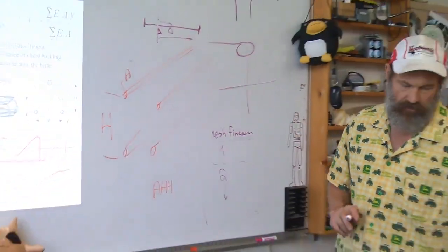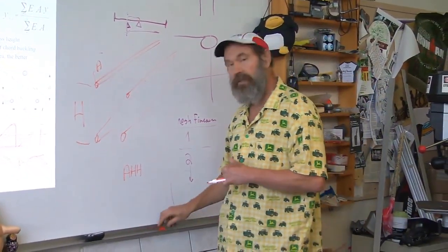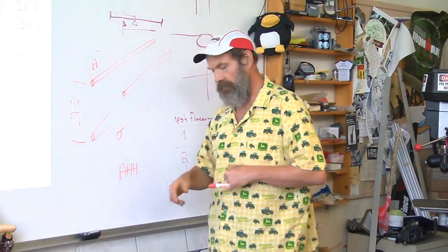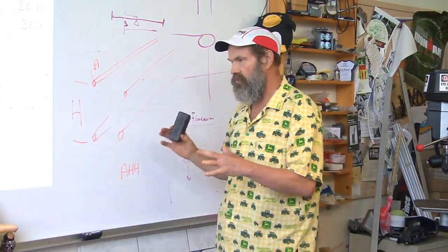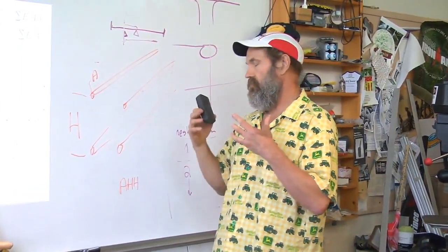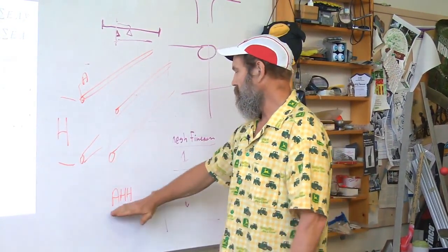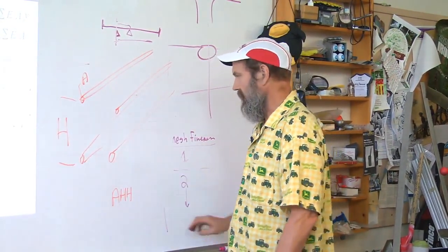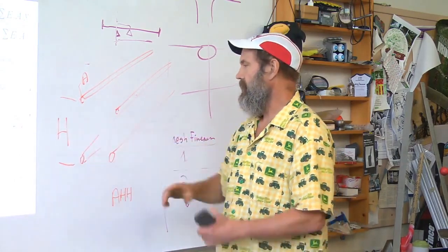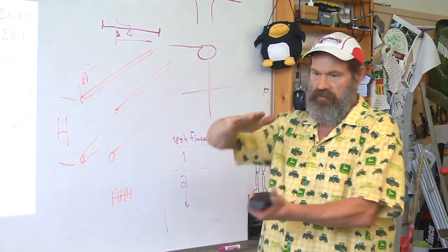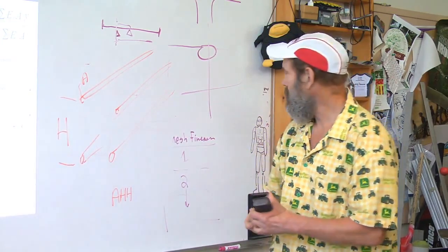Well, it gets back to the stability question of buckling. So remember, for initially laying out your estimate of the strength and stiffness of the truss, you can use your estimate of the moment of inertia based on the neutral axis and the cross-sectional area. That lets you lay out your machine in terms of the size or depth of the truss.